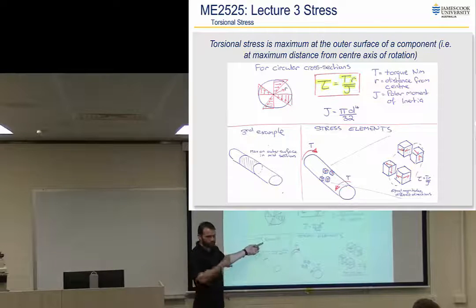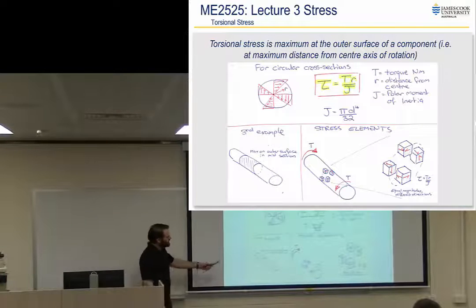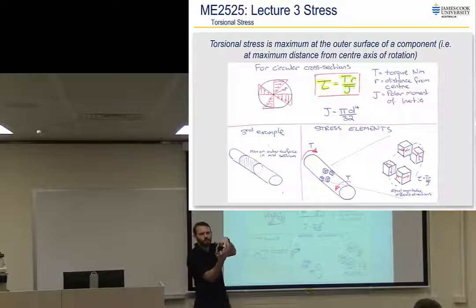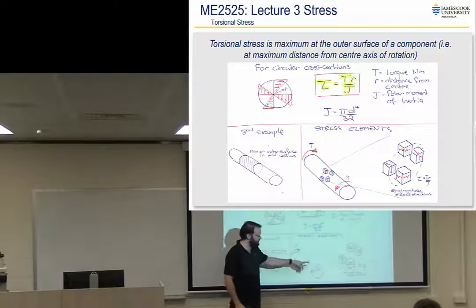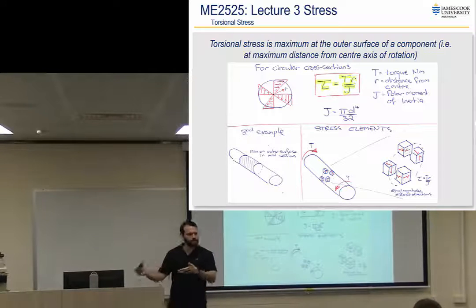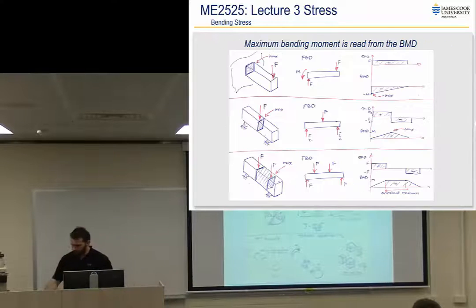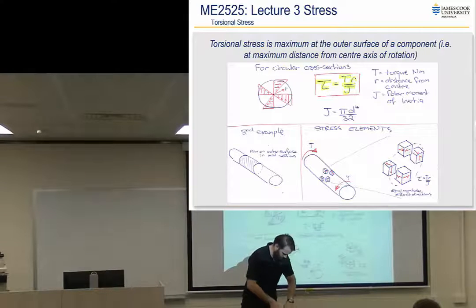So for the third example from what I showed, the bottom example there, somewhere in this section where I've shaded that outer surface, because we know the outer surface is maximum, and in that central section where T is even, anywhere in that surface, we know that our torsional stress is maximum. And just to calculate it, what we might do is draw 4 stress elements like that, which would add to 4 stress elements from whatever other forces we have. Now, an interesting little exercise. There's some rounds out here.